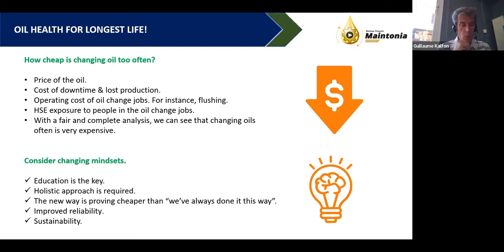And then finally, if you do all of this right, you will still have aging, because aging is a fact of life. It's unavoidable. And what we see in turbine oils and hydraulic fluids is that the way aging happens is that you lose antioxidants. Antioxidants are the chemical components, the additives in your fluids, which give them their long life. But the antioxidants sacrifice themselves to fulfill their mission over the life of the fluid. And then at some stage, you don't have enough antioxidants left in the fluid.